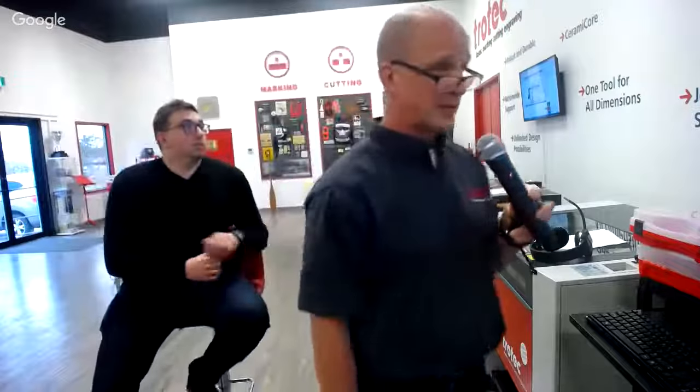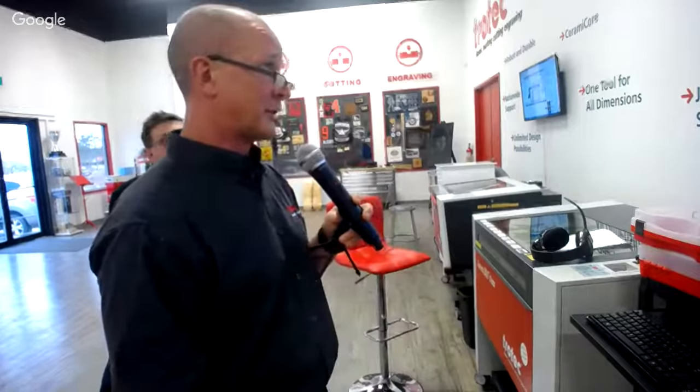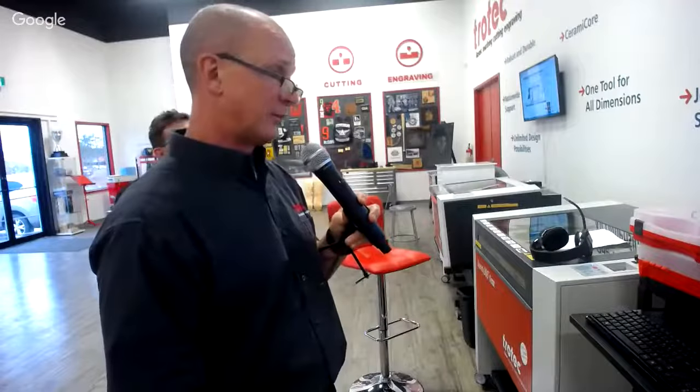I have done rubber stamps both ways, with and without air assist. You have to be a bit careful when using air assist, because if you've got a fair bit of dust on rubber stamps and you're using a lot of air, you're going to blow the dust around in the machine. So it's certainly something I would test, to make sure you're happy using the air, or maybe it might be better just not to use the air.